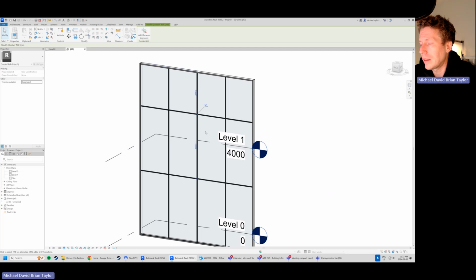So if I wanted to modify this, the mullion is going to follow where that curtain wall grid has been set up. And if I was just to try and modify it now, I'm going to end up with an error. The reason is you can see this little pin here. That means that things have been set. It's been pinned. You can't change it. So let's just go ahead and try this. I don't think it's going to let me do it. Let's change this to 3000 from that witness line. Let's change this to 3000, hit enter. You're going, my goodness, why isn't this working? Pulling out your hair, hopefully not getting too upset.